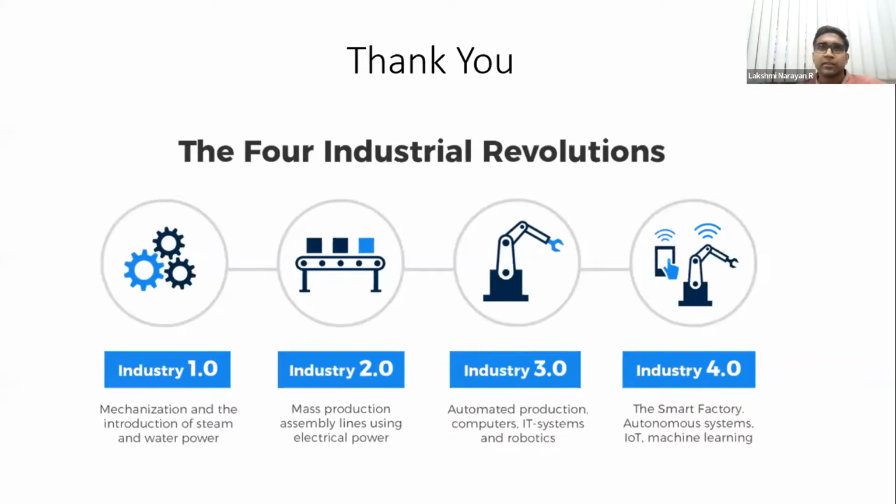Yeah, I think you are right. It can be used. It definitely is something which people are working on. Microwave technology right now is much more used for ceramics because it does some kind of sintering. Now with sintering, there are some issues. If you don't completely melt it, of course, there are going to be issues. If you melt it, it's a different story; you have solidification things coming in. But if you're just going to sinter the material with some kind of energy input, then there are problems, because with sintering you can never eliminate pores. You can never have full density. So that kind of problem comes in. But if microwave technology can be used to melt the material, sure, why not?